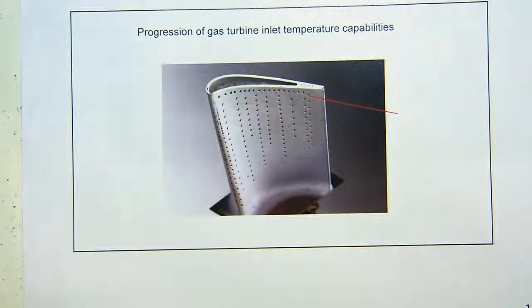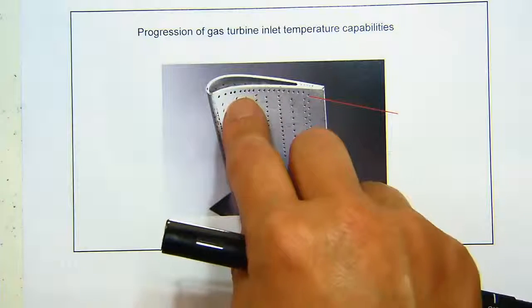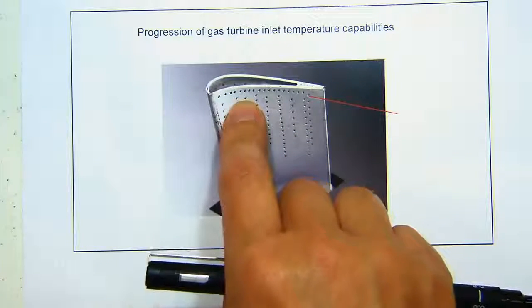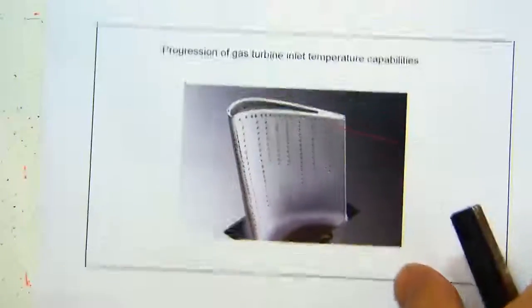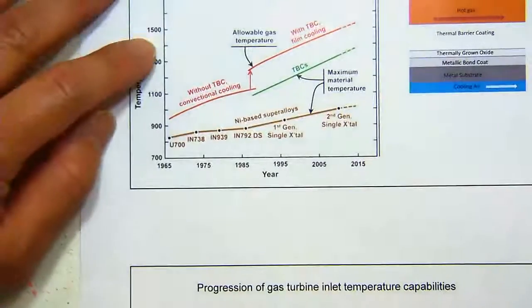They are not coming out as a high velocity jet, but at a relatively low velocity, and they can stay near the surface and form something called film cooling. You form a film of air on top of the surface to basically isolate the high temperature coming directly from the combustion outlet. So those are different technologies already being used, allowing the temperature to go close to the flame temperature.